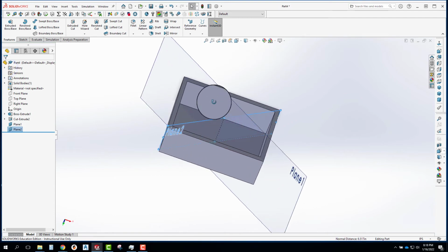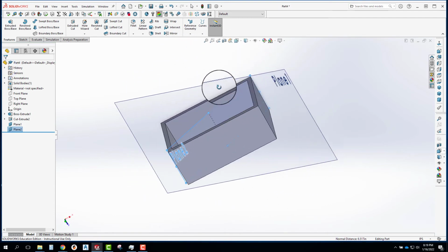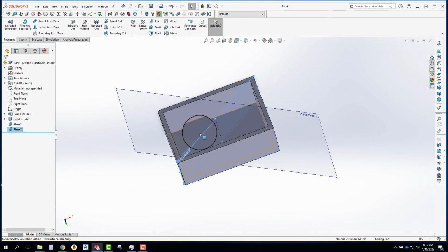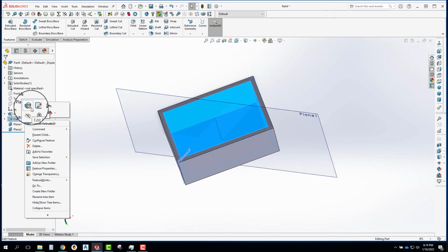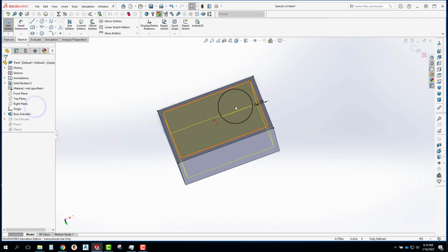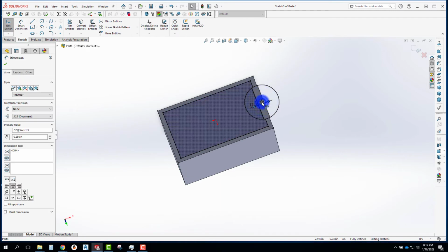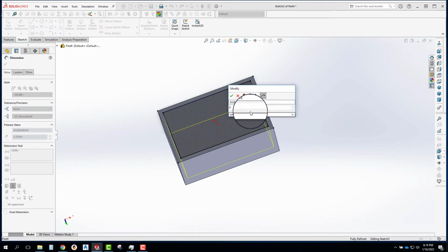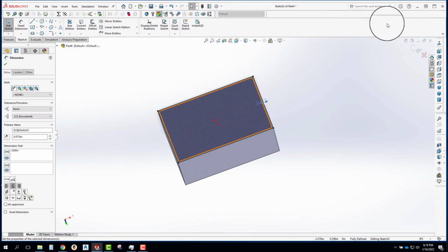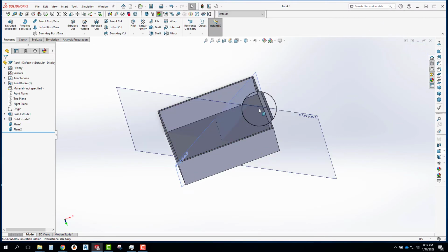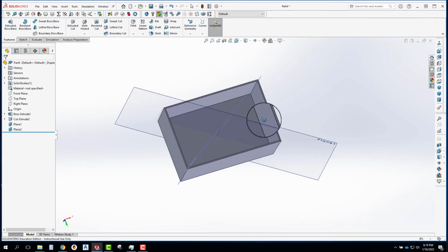Now I'm going to sketch on these planes where I want a rib. I want a rib that kind of braces down. Maybe rather than having this thick 1/4 inch wall, I want it to be a pretty thin wall. Let's say maybe it's 0.075 inches, a really thin wall. So to keep those walls from buckling, I'm going to brace it in the corners.